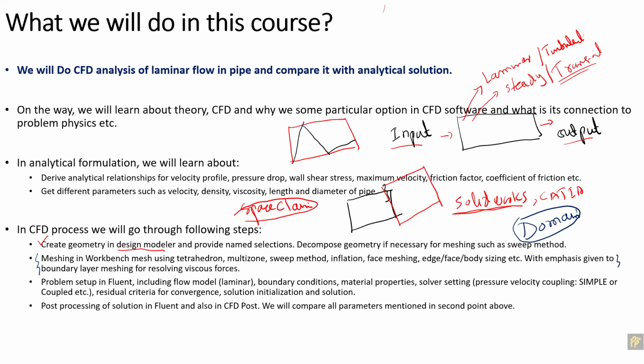how to decide about that thing, what should be the y plus value, what turbulence model you are going to run based on that mesh. So for that particular turbulence model, which mesh should be there. So these things are discussed here, not only the meshing software itself, but the meshing aspects also. Okay. And then we set up the problem,